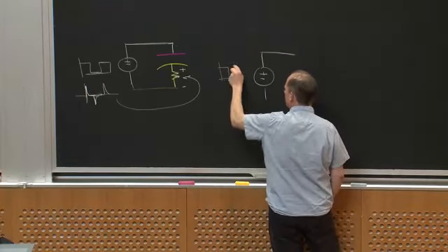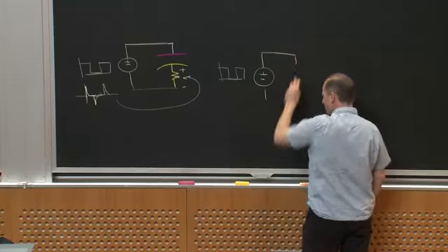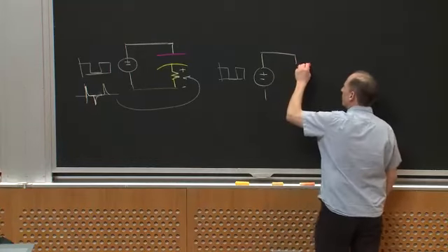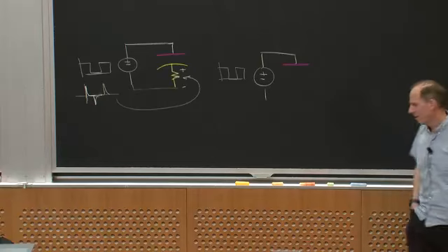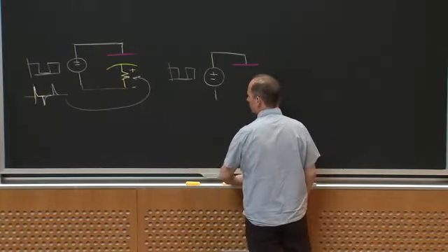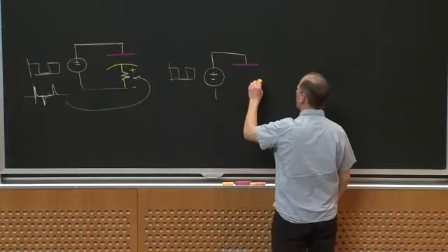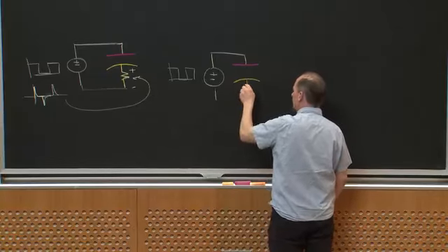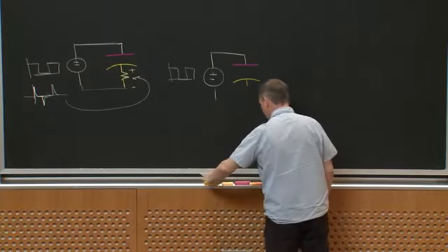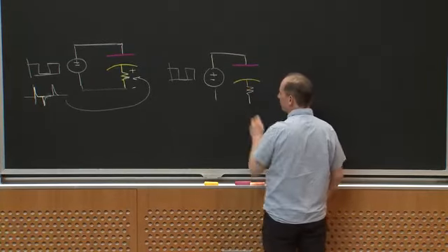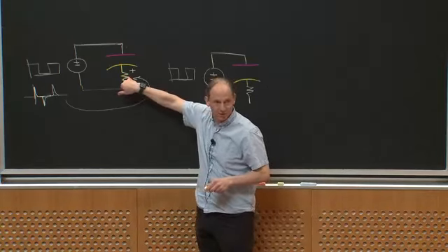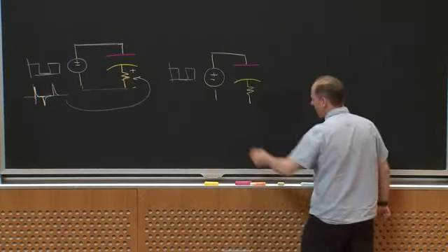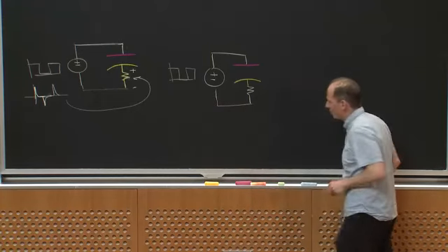It's switching up and down. I've minimized it, but I've still got a certain plate area there, and I need some area for my switching node, and it's still going to be a high impedance node. The other thing I can do, by the way, is if I make this resistor smaller, that starts to become less nasty. But there's only so much I can do about that.